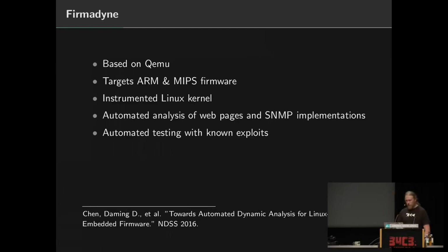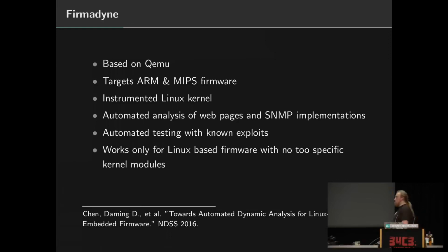Yeah, unfortunately, the downside here is that it only works for Linux-based firmware, and only if there are no specific kernel modules around. Because if the embedded device needs to do hardware interactions with specific hardware peripherals, this will most likely be done via specific kernel modules. And if they can't be emulated, Firmadyne fails to succeed.